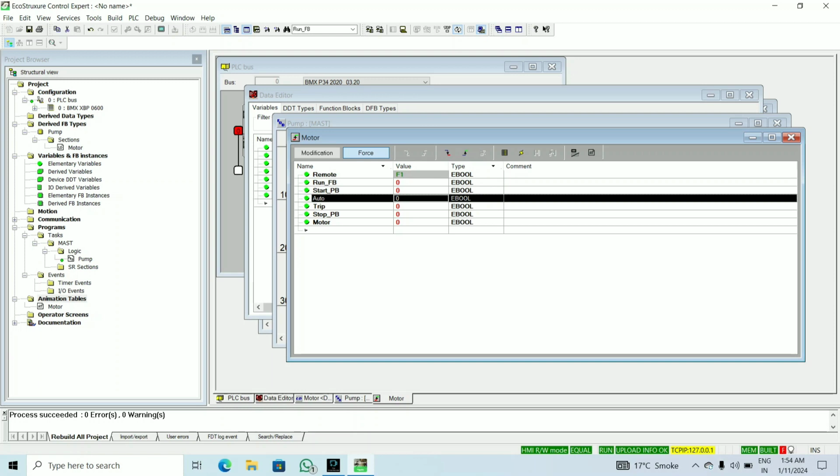Go to the MCC panel, you look at a selector type switch. This has three types of function: field type, remote type, and local type. If you select the remote side, the command comes from the actual PLC. Go to the SCADA screen, HMI screen, select the input command and give an input command. If you select local, then you cannot give a command from the HMI screen or SCADA screen in the PLC.